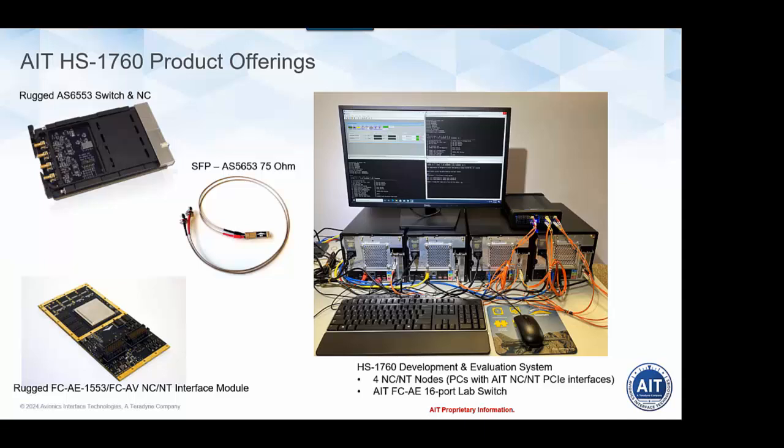Some product offerings that AIT has related to high-speed 1760. We offer a rugged AS5653 compliant switch and network controller. It's a 4-port switch that also has an FCAE 1553 network controller built into it. We also provide a rugged XMC-based end node, an interface module that could go in an HS1760 node. That provides support for FCAE 1553, both network controller and network terminal operations,